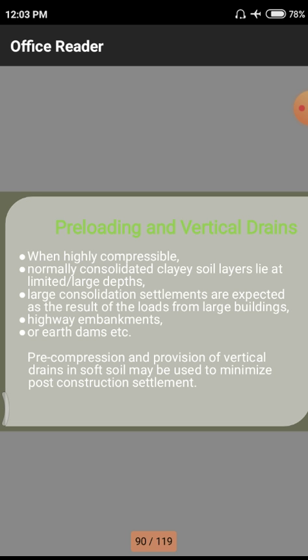An apartment might be a simple 5-story building, but a large building is a 10-story or 20-story building, whose total weight is focused on a particular part of the area while the remaining area is free without any pressure. The total force exerted by the building has to be borne by the soil within a particular limit, so a huge amount of settlement will occur on a particular portion, and we need to employ these preloading techniques.